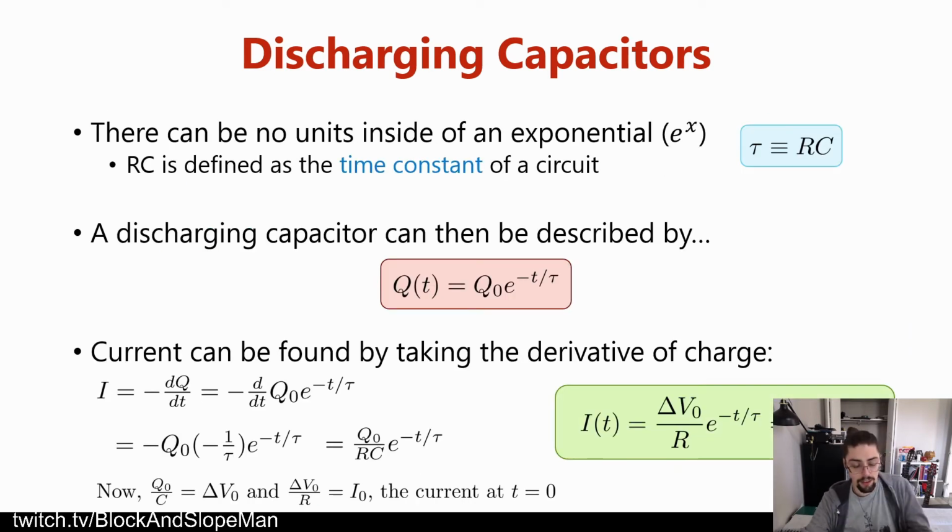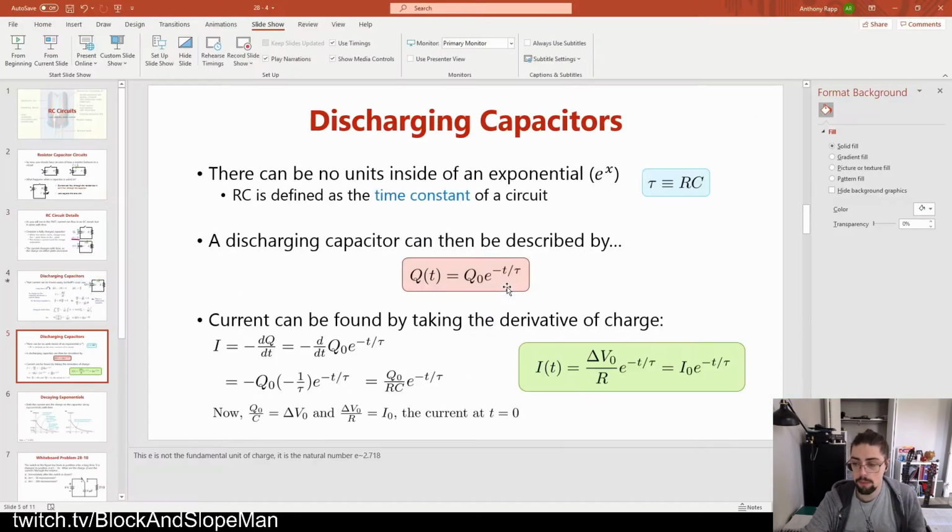So we can take it like this, and let me go back out of this now. I don't want to keep those ink annotations. Let's go back to this so we can actually see this. Here's our big equation, right? Highlighted now in red, what we just found on that previous page. We're going to call this value RC our time constant. And this is a little bit of a tricky thing because ohms times capacitance is not necessarily seconds, but we're saying that it's equivalent to these two numbers. If I put these two numbers together, I'm going to call that tau, and tau is what I'm going to now refer to as my time constant.